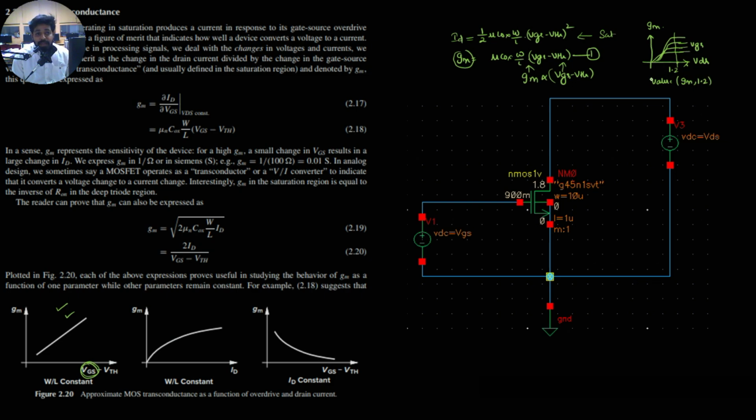So when I'm extracting all these values of VGS, VGS of this one, this one, this one, VGS 0.6 will be taken as a graph with VGS equal to 0.6, VGS equal to 0.7, VGS equal to 0.8. All these values will be monitored here, and it becomes VGS as the x-axis. The corresponding GM changes we will get on the y-axis. As the VGS increases, the GM value increases, so we will be getting a graph like this. This is the graph expected, which is there in the textbook. So now let me do the simulation to get this graph.